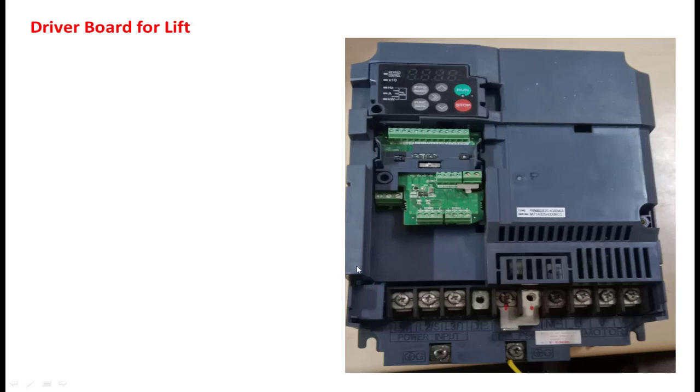Now here we are going to observe that from these four terminals we give the connection to the three-phase induction motor, where the stator winding is connected in star. That's why the neutral terminal is also there. So these four terminals we connect to the R, Y, B and neutral. In the same manner, here three terminals are there along with the neutral.